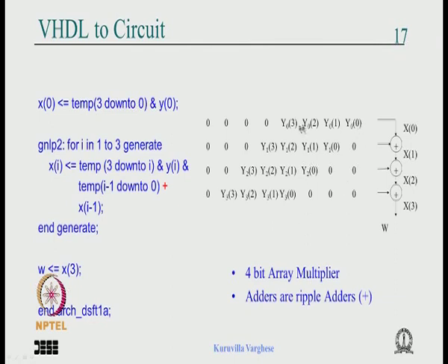Here you know that when you add this there is a rippling here, then there is a rippling here. It is possible to avoid the rippling because the idea is that say you are adding these 2 bits, it does not matter whether the carry comes here or here. So it is possible to put the carry of this stage along with this here.